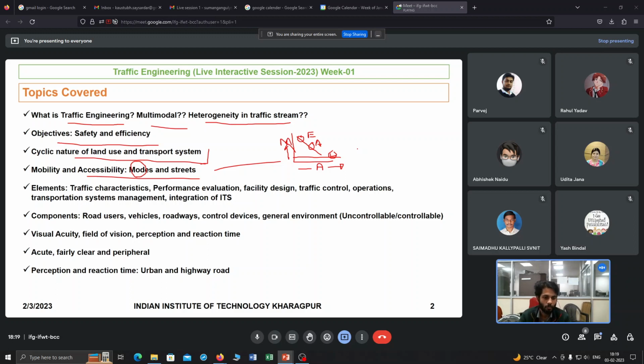And what is F? F means your level of service has already failed, queuing is occurring, and you are stuck in the traffic. Like we always hear the news about Bangalore, right? There is congestion, and long queuing is observed. So you can think of those as the levels of service, and in between are B, C, D, E.